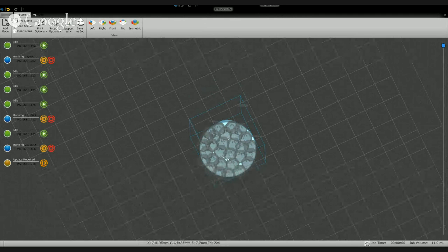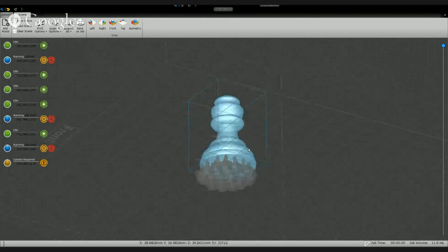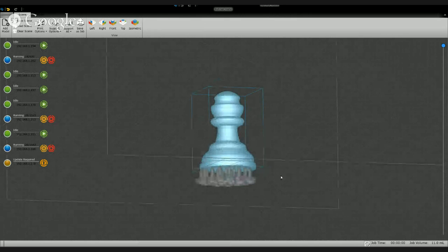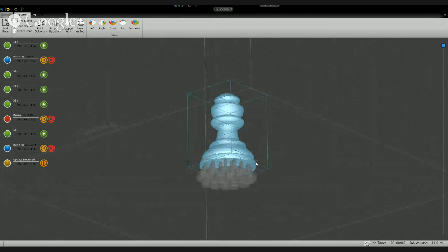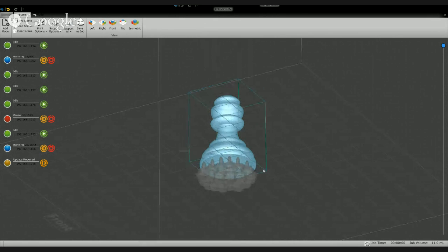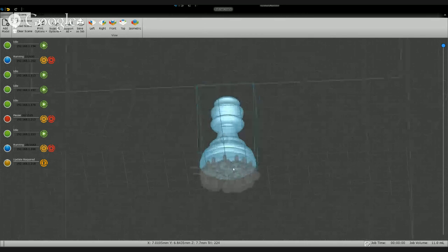So the reason that there are so many supports on the bottom is because with big flat areas like this, you need to have the supports tightly packed, or else during the printing, the weight of the resin on the back of the freshly cured layer will push it down and end up warping material, and you get little bubbles of uncured resin sometimes if you have large enough gaps. So the supports need to be fairly close together, especially for flat layers.